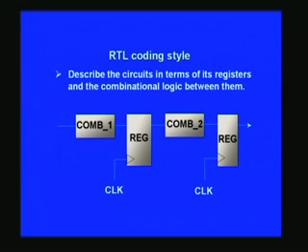And basically RTL coding style is once again the same as synchronous design as such. You have a combinational circuit, and it can be any complex combinational circuit, and then follow this with a register, registering this combinational output as such, and this may be an intermediate output as such, and then follow the same pattern successively, and this keeps going in this fashion, and data flows in this fashion naturally.